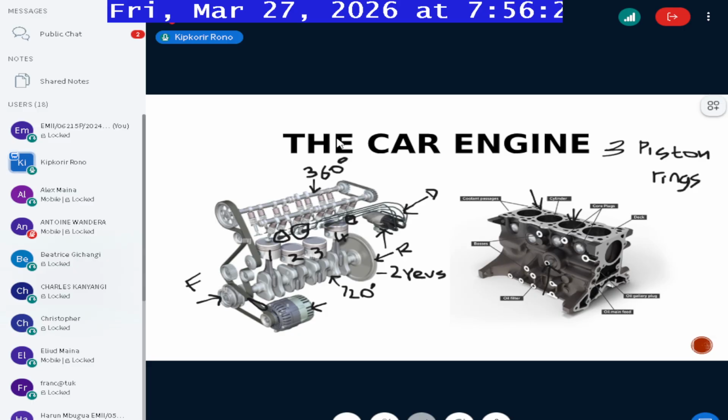So an oil change can also be based on things like, for example, the mileage. Okay, it can be based on mileage. There are some that are recommended to be changed after, say, 5,000 kilometers, 3,000 kilometers, 8,000 kilometers, depending. You'll get some type of oil, for example, the semi-synthetic can go up to 5,000 or 7,000 kilometers. Fully synthetic can go as high as 10,000 or 15,000 kilometers. So it really depends. Now, usually an oil change is accompanied by a change of the oil filter.